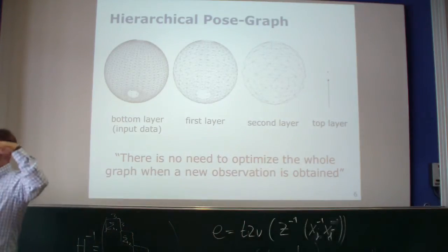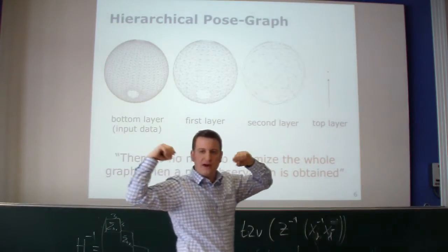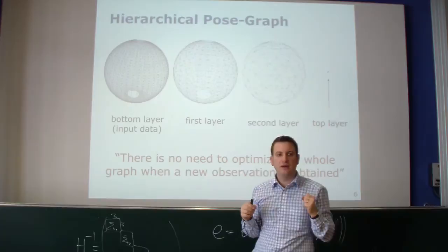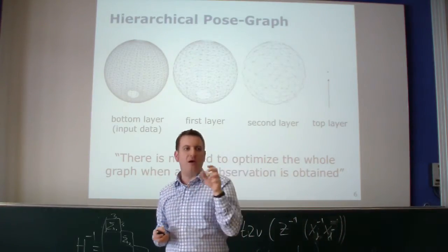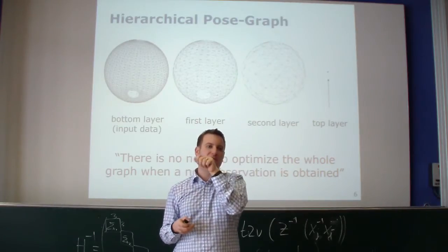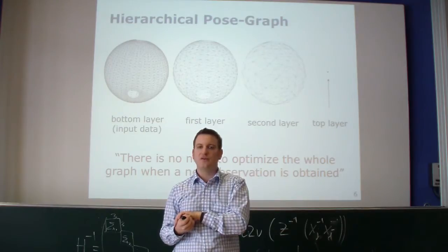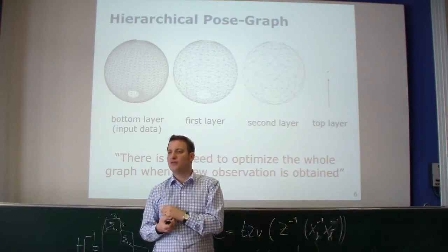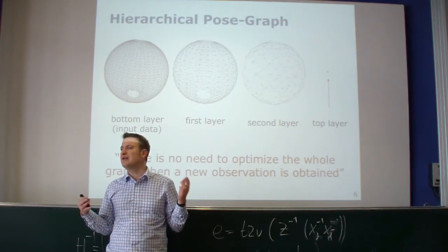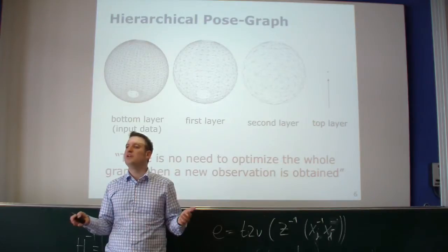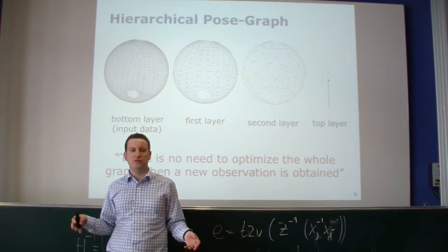So the idea is to only do corrections on the higher levels, to correct the raw structure of the topology of the scene, and only in areas where I really want to, for example, do my data association, I go down to the lowest level and then search in this lowest level for constraints, for data associations. So the key trick of that hierarchy is to pre-filter the majority of nodes which are currently not of interest, because the robot is only interested in its current pose, its local surrounding, in order to do a data association.